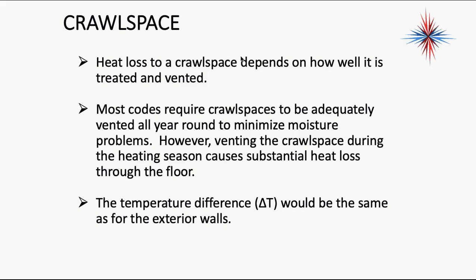Heat loss to crawl spaces depends on how well it's treated and insulated. Most codes require crawl spaces to be adequately vented year-round to minimize moisture problems. However, venting the crawl space during the heating season causes substantial heat loss through the floor.